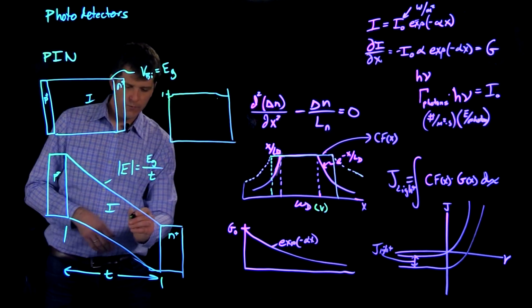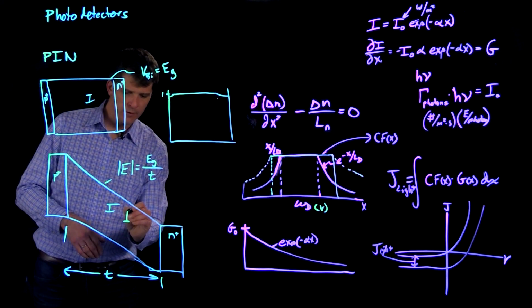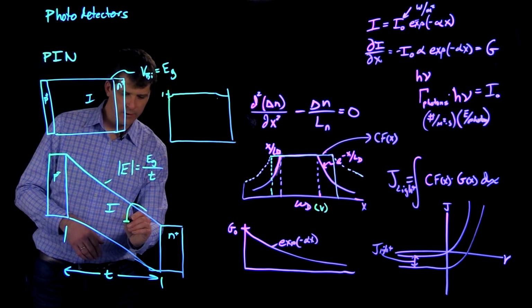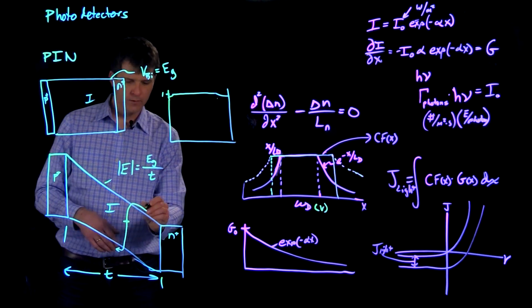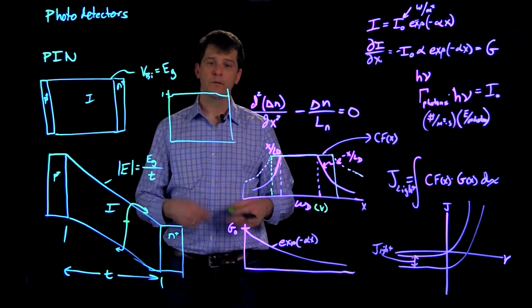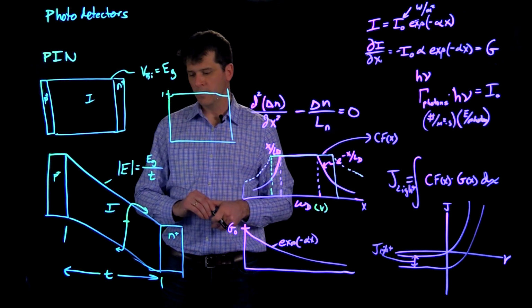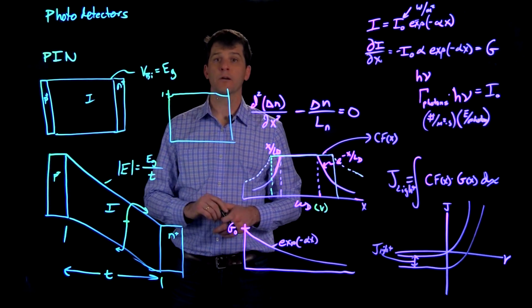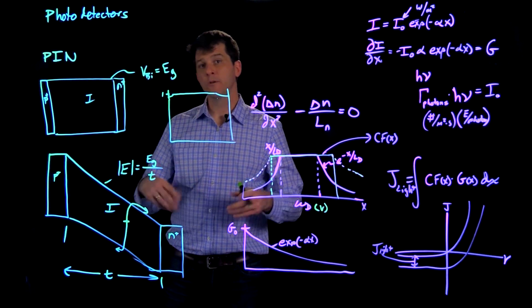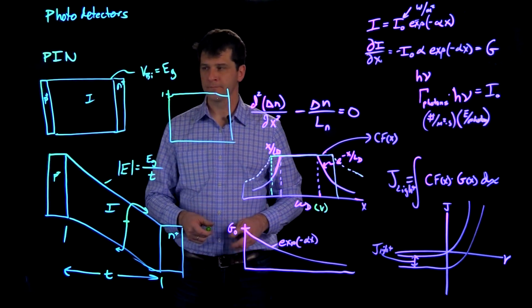And the last thing you have to think about is additional dark current being generated from traps inside the depletion width. So if there are defect states coming from impurities or bad crystal growth, those can add to the dark current and thus reduce the signal-to-noise ratio for your light current.